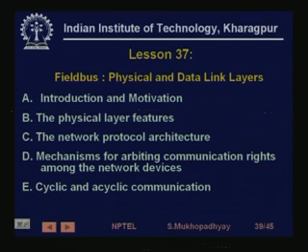Otherwise, when some device is transmitting data on the network, if another device starts transmitting some different data on the same network, then the data can get corrupted. So, we took a look at some of these models of arbitrating communication rights on the buses, and at how that actually turns out for cyclic and acyclic communication.